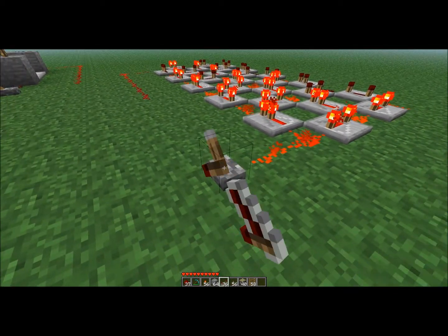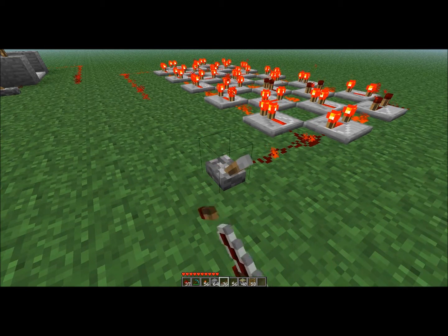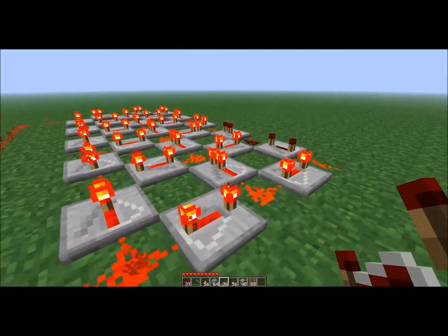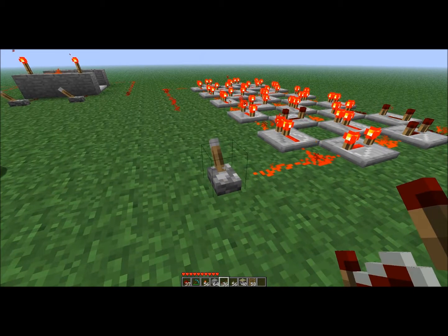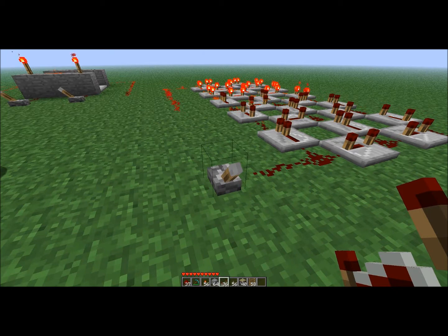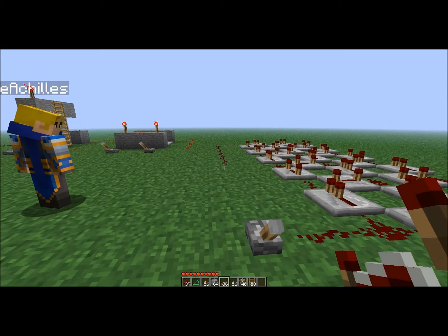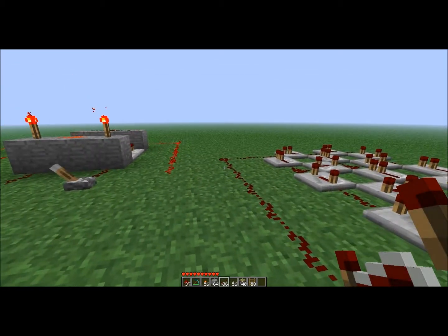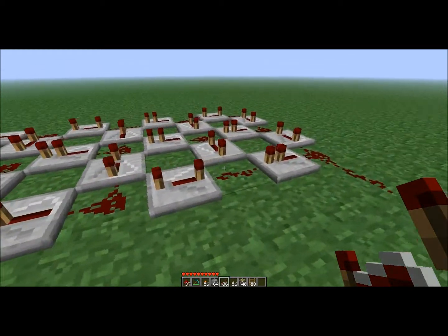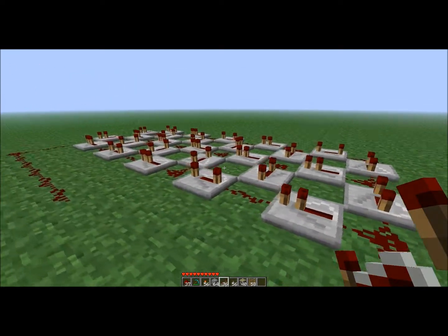But if you try to toggle it in the middle, you can see that the off signal does not propagate down really far at all, and unless you let it travel the whole delay, it doesn't turn off, which is important for this specific reason, because you don't want it to open while the water's there. So that's this design. Hopefully you could rebuild it if you try. It looks complicated right here, but it's not too difficult to make.